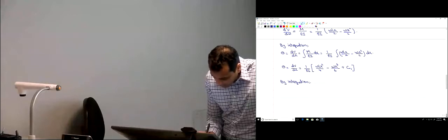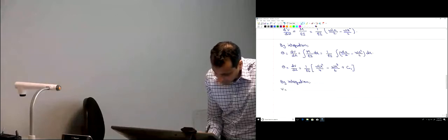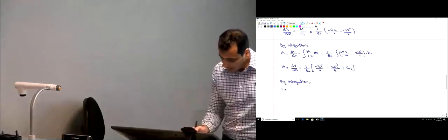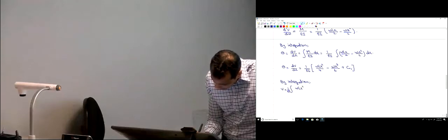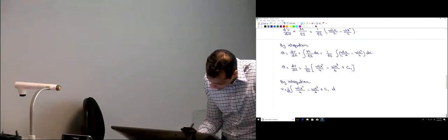You're integrating theta now, so you're going to have V. You're integrating dV by dx, you get V. So now I'm going to integrate this, okay? It's equal to the integration 1 over EI, WLx squared divided by 4 minus Wx cubed divided by 6 plus C1 dx.